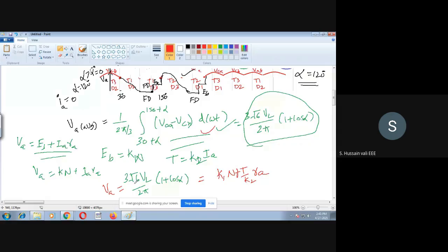So now we can draw the torque speed characteristics. I'm sure that they are very same as the single phase case. Whichever torque speed characteristics you got in the single phase case, here also you will get the same. Only the magnitudes may vary. The graph something like this you will get here, for alpha equal to 0, alpha equal to 30. This is the graph you got between speed and torque.